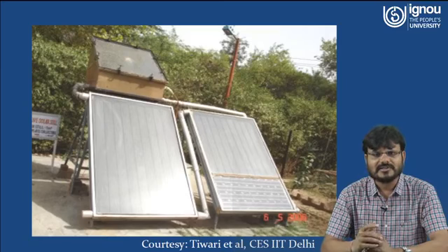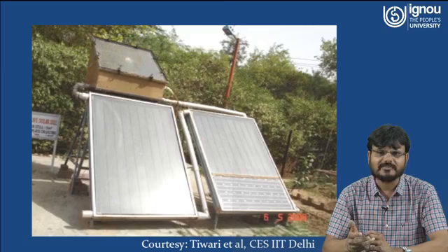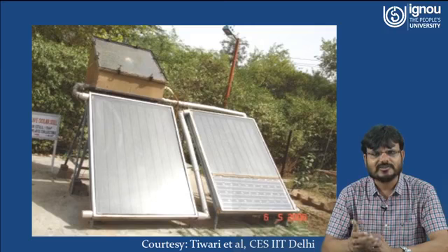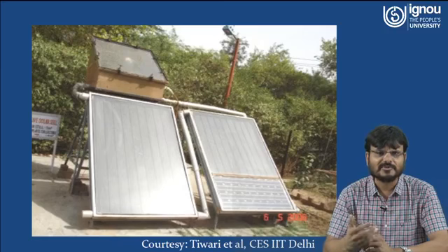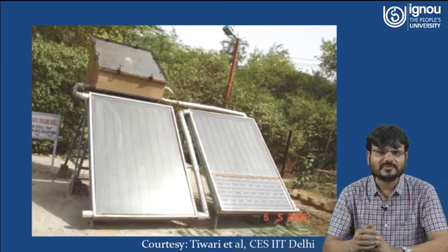Here you can see in the first chamber, below the chamber there is a transparent PV module which is used to operate the DC pump, which will force the water inside of the hot water collector, and this hot water will be transferred to the solar still. So it will increase the temperature of the evaporative water. So more evaporation will occur. If more evaporation occurs, this water will reach the glass cover of the solar distillation. It will be condensed. That means you can collect more pure water at the outlet from the solar distillation.